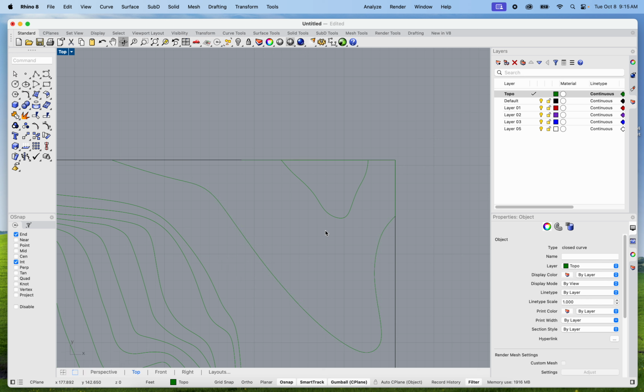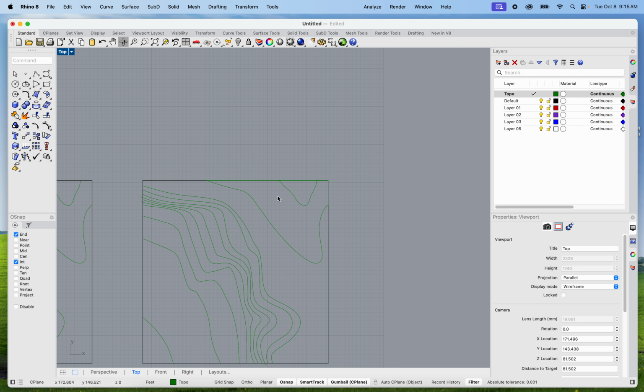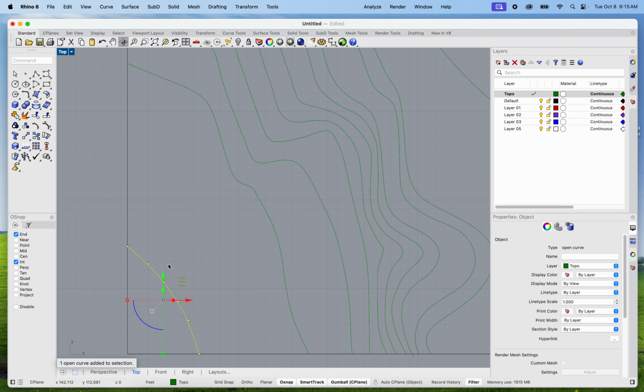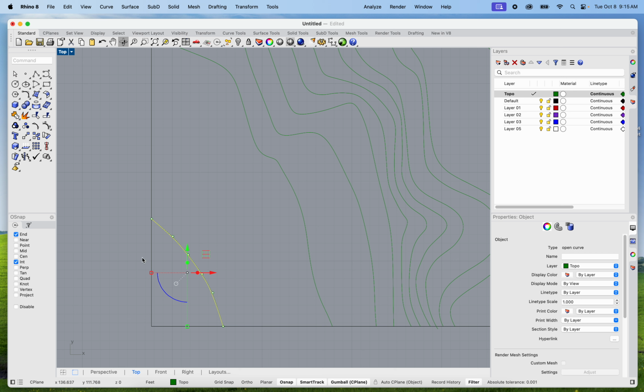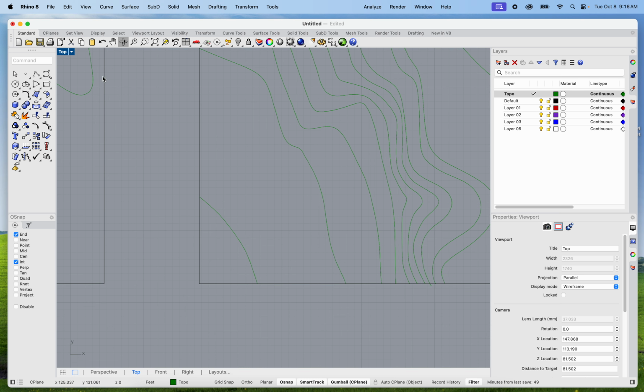Join. And as you can see, I already have 1 complete and 2 complete. Now, to be fair, there is actually a little trick. However, it doesn't always work. So for instance, I can close this curve because technically the computer sees a straight line as an open curve, right? It's not closed. However, if I type in close curve, it'll automatically close it for me. Now, to be fair, that's not the way that I want to close it. But again, I like to throw some things in the mix because you might pick a topography surface that does apply. Anyway, just want to throw that in there.